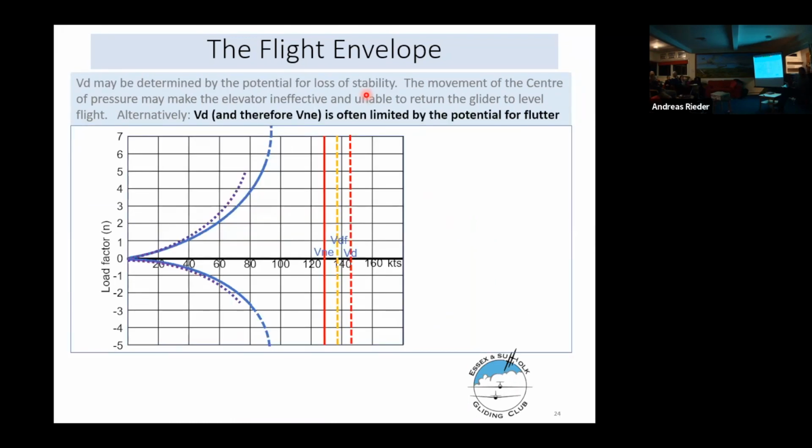Can I ask a question, Jonathan? Yep. If you fly faster, you would typically trim forwards. Yes. So you're decreasing that downforce on the tail in order to fly faster. Those physics would suggest that you need to increase it by pulling back as it is.